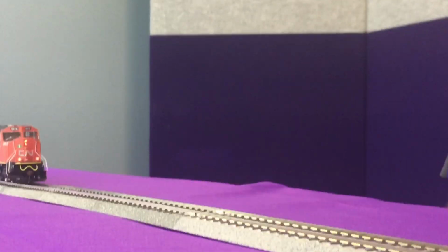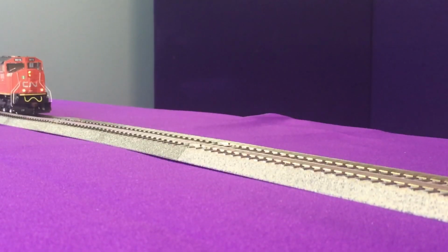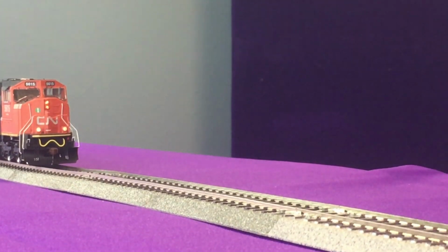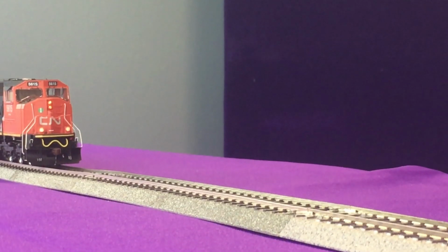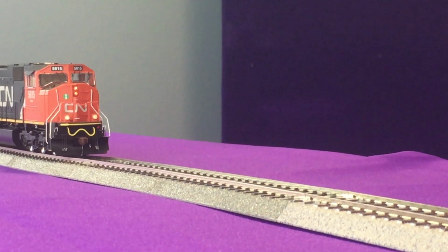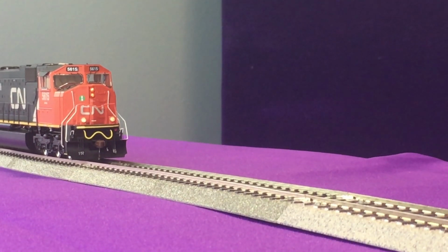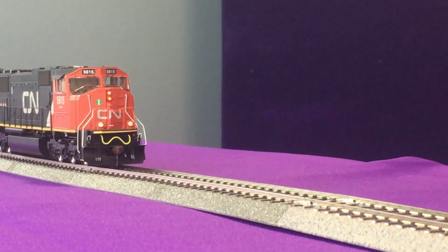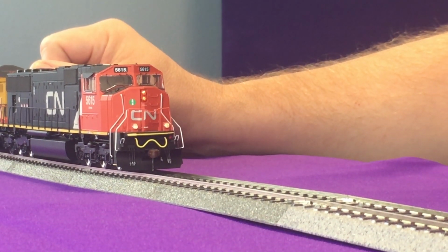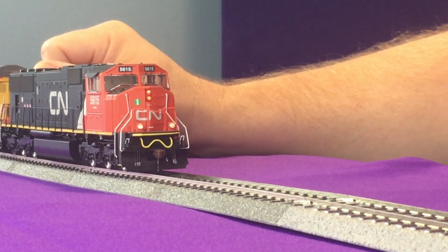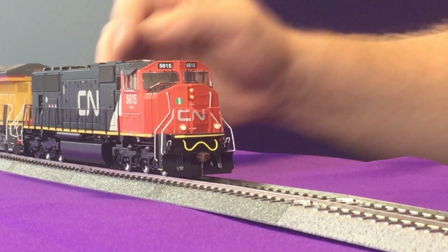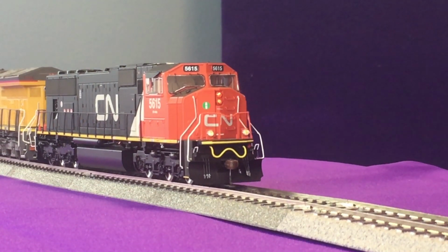So now once we've adjusted the timing and everything with the DDE, let's see how this plays out. We've got two locomotives here consisted together. We're going to move them forward at about speed step 3. And you can kind of hear them throttling up a little bit and then back down. But once we've got this tuned in, we're going to put a little resistance on here. And you kind of hear how they work together, sharing the load and also making sure that they're more in time together with the notching.